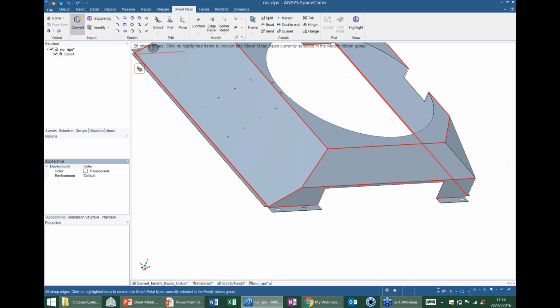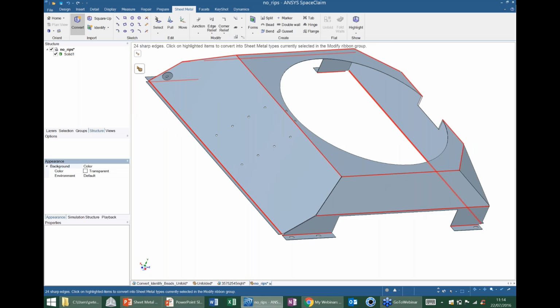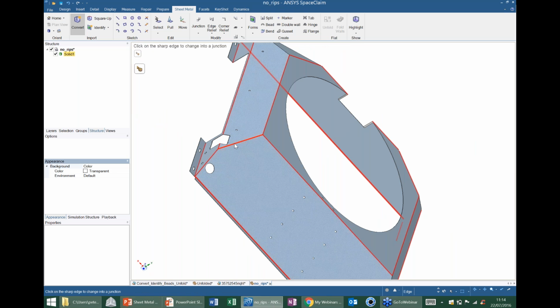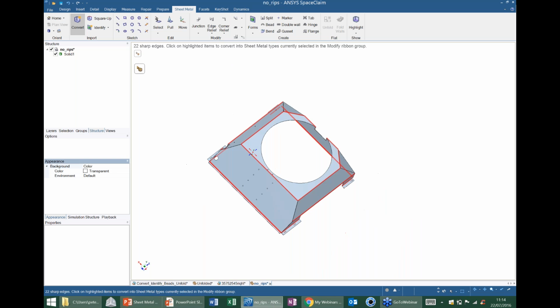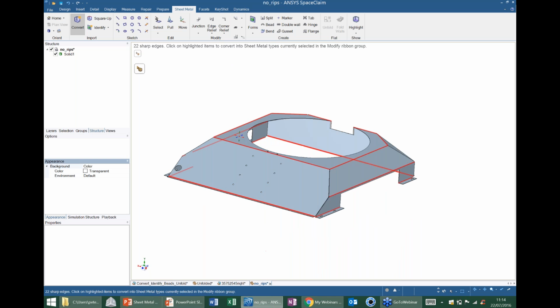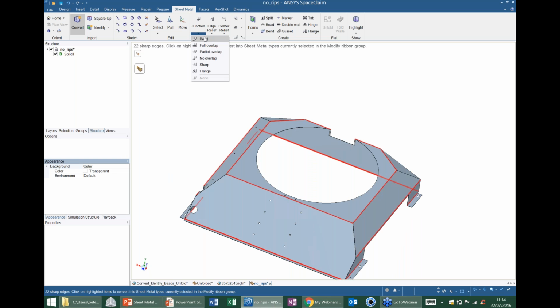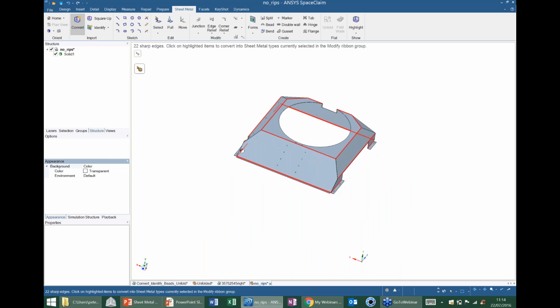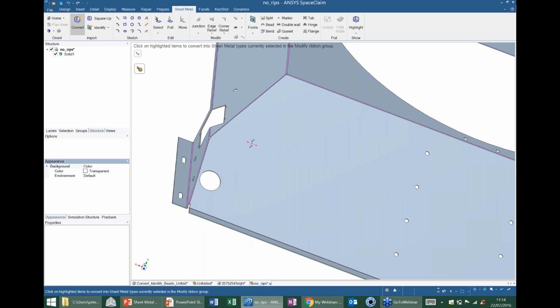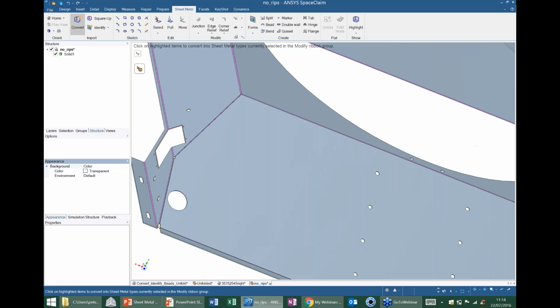And then finally on the other side. And then the rest of these areas here, these sharps here, I think I'm just going to have them as bends. So I can do a quick box select over all the rest of that, and that will convert that now into something that will unfold quite happily, in theory.